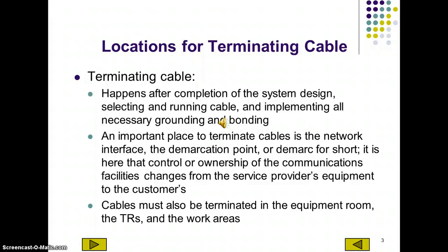It's a very important point to check for problems. If you get reports of network problems, in particular talking about voice networks, that would be a prime location to go check and verify the symptom. The reason being is what you would do is disconnect the inside plant cabling and connect directly to the outside plant, thus verifying if the circuit is working from the outside provider.